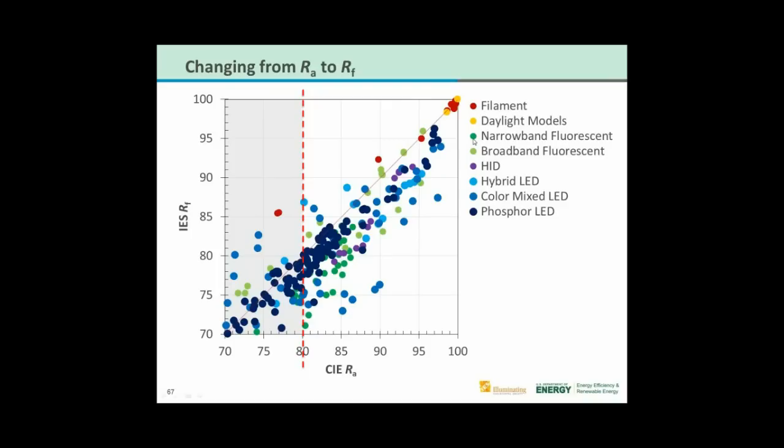Narrowband fluorescent, that's most fluorescent you'll see in offices that are recently designed at least. So that's spiky distributions with triphosphors. Broadband fluorescent, if you have old T12 lamps perhaps, they might be broadband fluorescent. They use a different set of phosphors that were broad emitting instead of very spiky. They're less energy efficient, but you can see that at least according to this chart, their scores don't drop as much because there was no real reason to optimize it because you're not moving those energy spikes around.